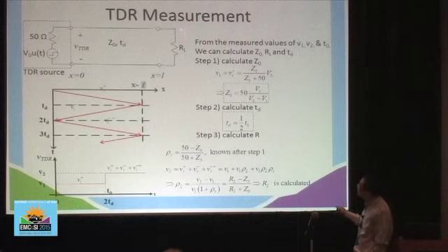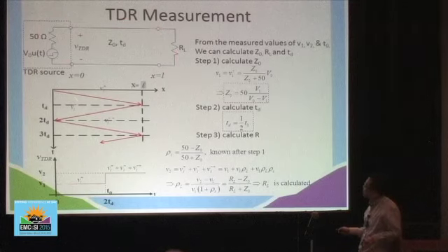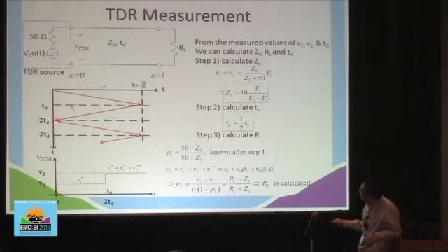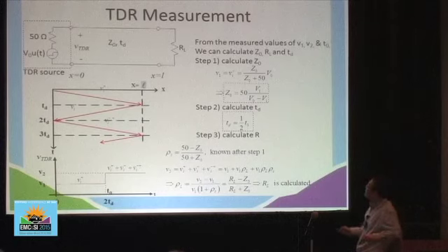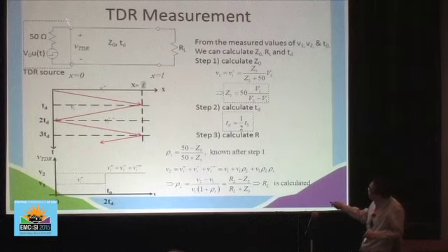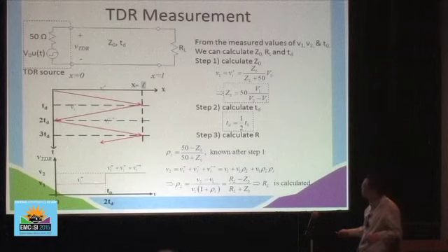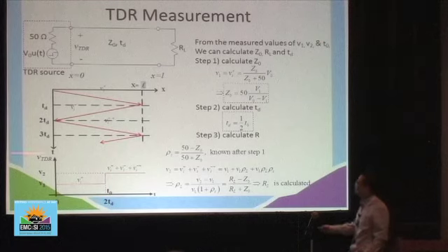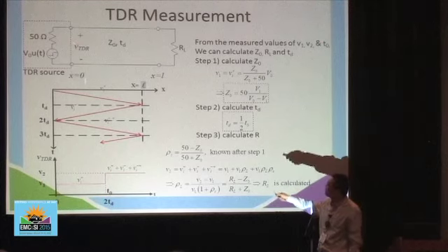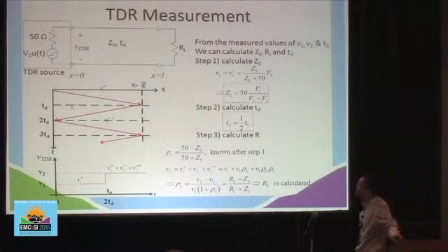So for this simple case, if we do the bounce diagram, we know initially we have a right-going wave. At the TDR, we generate a left-going wave. And this left-going wave, when it reaches the front, generates another right-going wave, and so on. That's the bounce diagram. If we draw the total voltage at this input side, this total voltage starts with a constant value of some voltage, and at some time it jumps to another voltage. Okay, this is what we can measure at the front end of the transmission line using the TDR.